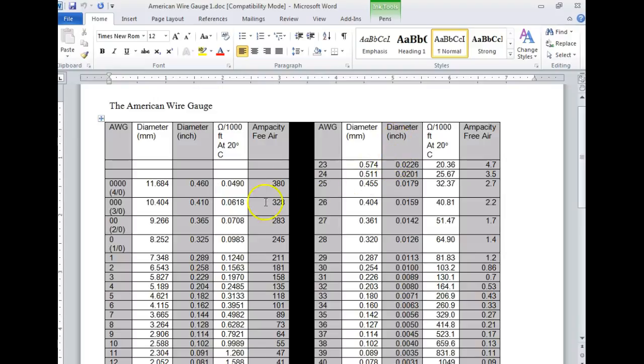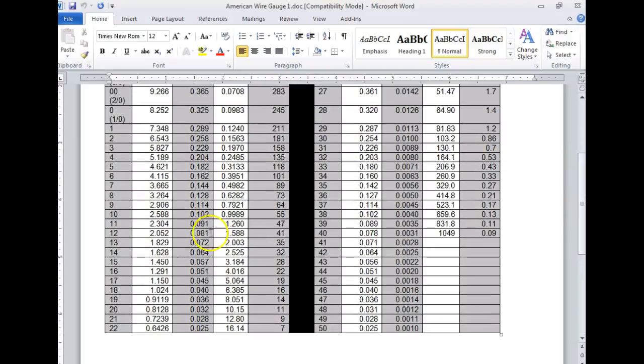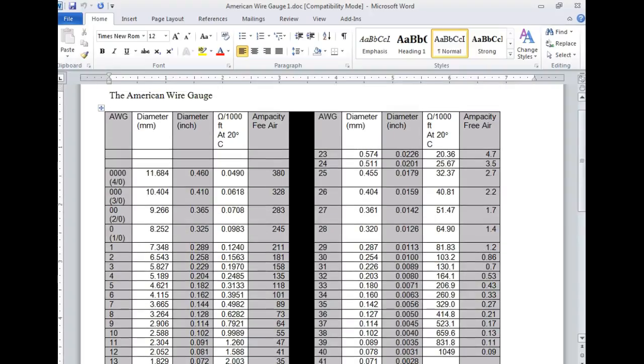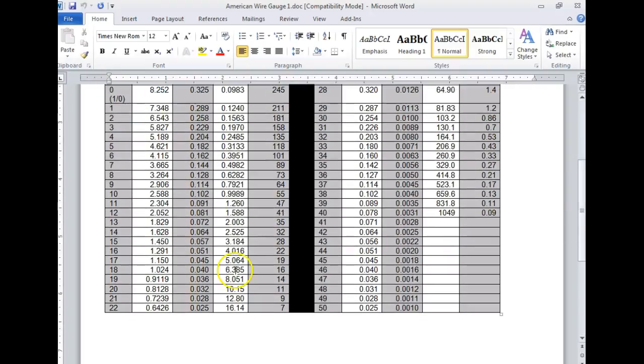So when we tell y'all in electronics that you need to buy some 22 gauge solid strand wire, this would be the actual diameter of the wire. And this would be the gauge in millimeters. Of course, over here we're still using inches, but the American wire gauge would also apply to a European standard too. But they wouldn't give the sizes in inches. They would give the size in millimeters. And then anything above 4/0 over in Europe, they call it millimeter squared. And we'll talk about that in a minute.